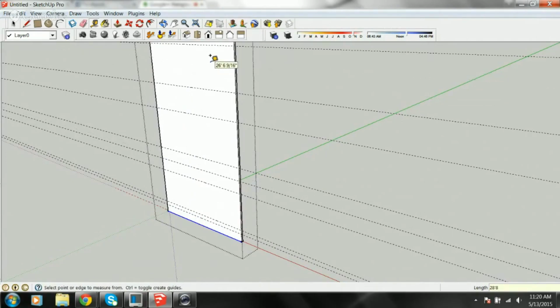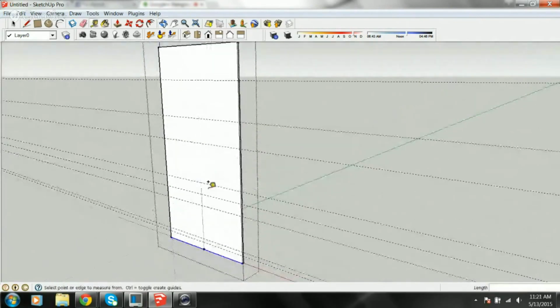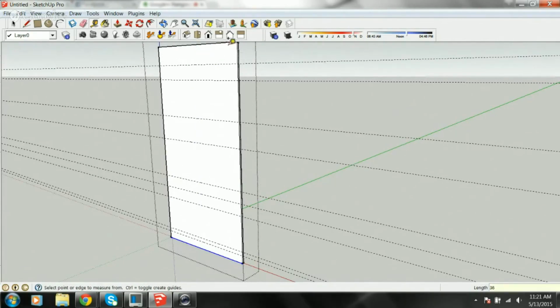You see, I'm just typing everything down in that bottom right-hand corner as I go here. So real quickly, you see all I'm doing is putting layout guidelines within my group. Okay, and then the next one was 30. I'm trying to point to my image here, so you see me go down off to the left. That's what I'm doing. I'm going to come real top down since my cornice line was at 31. I'm just going to come down 3 feet for 36. So that last 3 feet up here is just a guideline for me within this total wall plane of where I'm going to build my cornice.